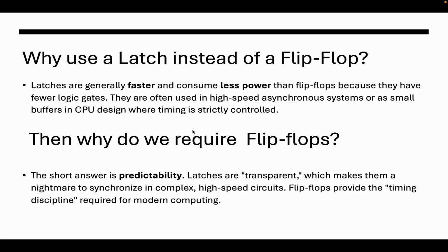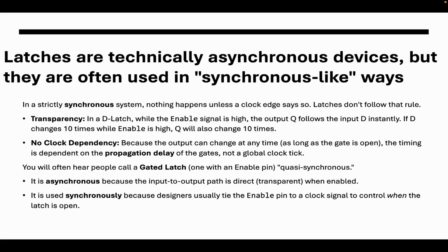Then a question might arise: when latches are better, why do we require flip-flops? The short answer is predictability. Latches are transparent, which makes them a nightmare to synchronize in complex high-speed circuits. That means for latches, since they are level triggered and asynchronous, it is difficult to give a proper timing discipline. So in that condition, we use flip-flops.